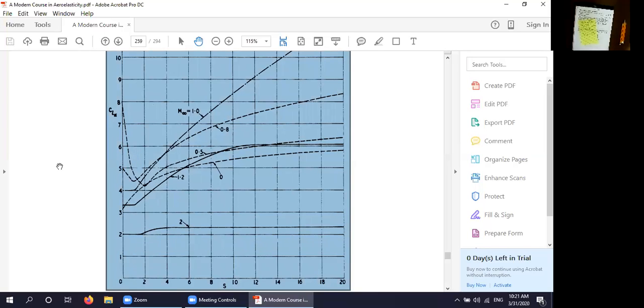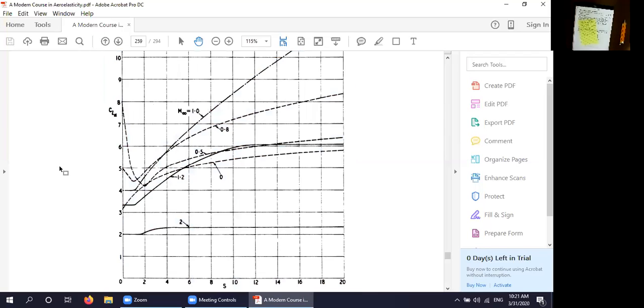And then let's look at some other Mach numbers. I'm sorry this curve is so busy, but it pays to pay some close attention. Here's the curve for Mach number 1. Again, piston theory actually gives you the right answer at short time. It's 4 divided by the Mach number, or in this case, 4 divided by 1, so it's 4.